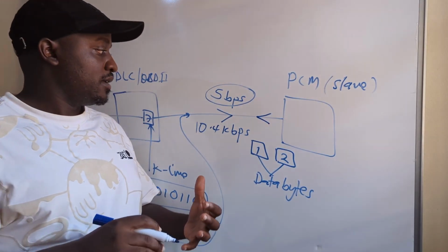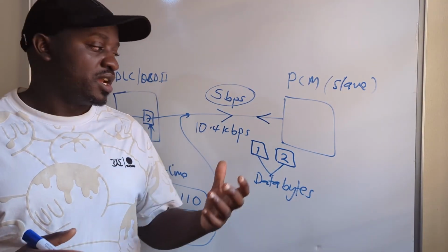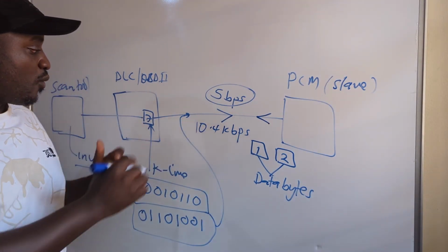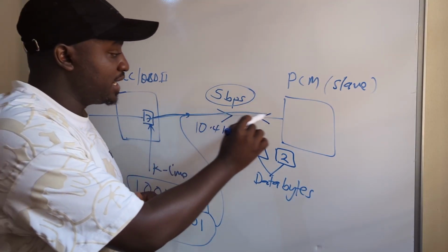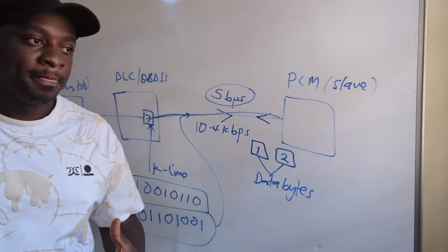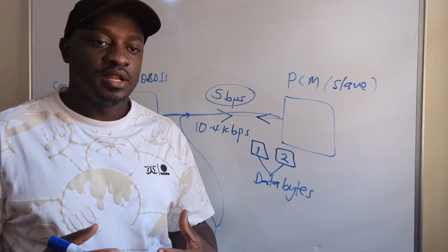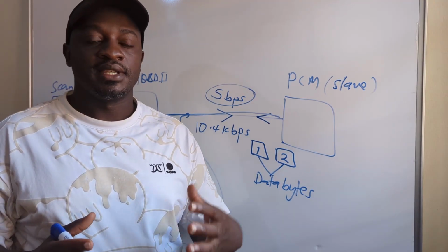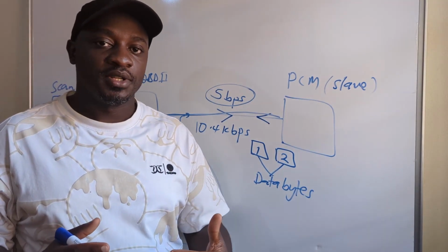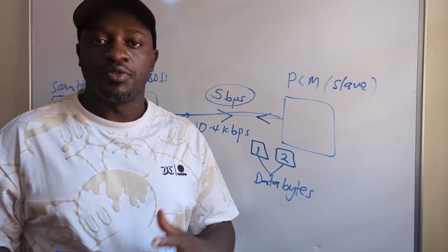And as we've seen, it's not different from that of a 2-wire, only in this case 1 wire, which is the K line, is utilized. Now, because this process is quite long, that's why it is known as slow initialization, and usually takes 2.5 to 3 seconds.